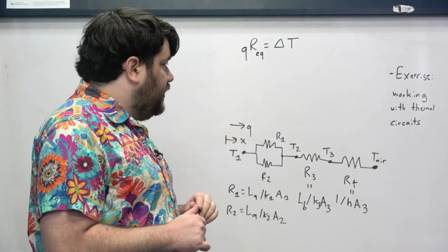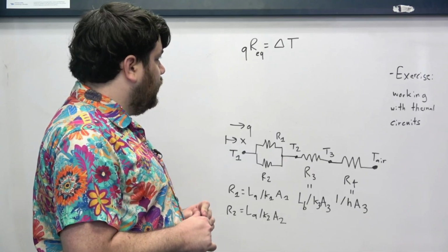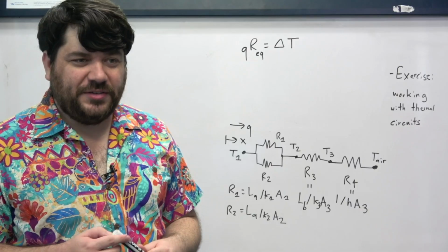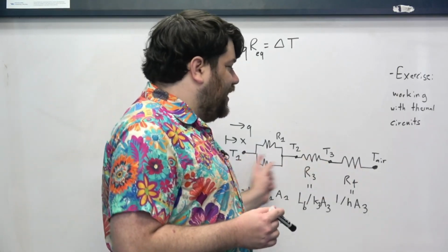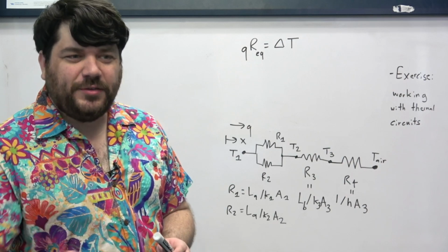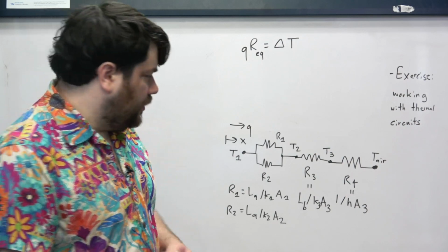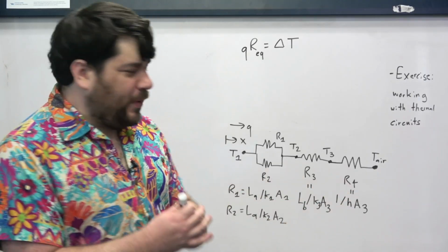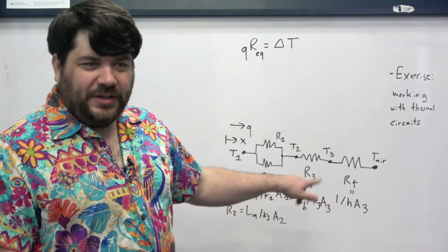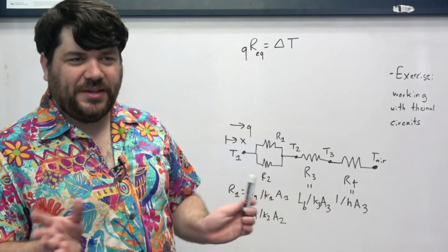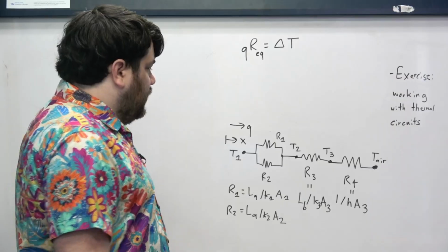And we want to figure out the Q. And we have to do that by calculating the equivalent thermal resistance of this entire thermal circuit, right? And this process happens via summation. So we have these expressions for R1, R2, R3, and R4. I'm not going to write down the whole things in the coming sections. I'm just going to say R1 and R2 and R3. Okay, so I'm going to keep it expressed in terms of that.